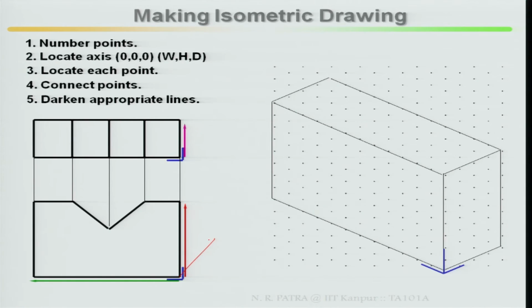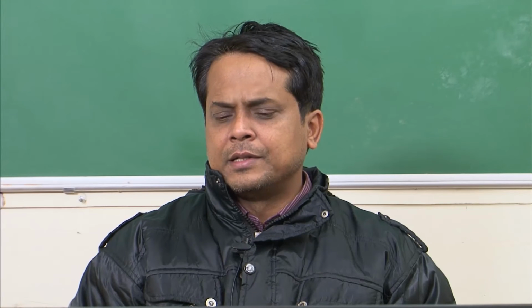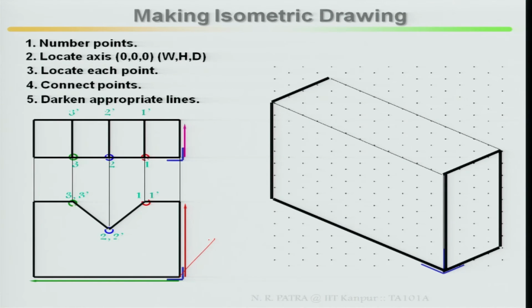It is very easy to draw once you have isometric grid lines. There are two types available in the local market. If you get the grid lines, stick to the one origin. With respect to that, you can take the grid lines. Once your isometric box has been finished, mark the points. So this is your reference or origin. Finish your isometric box, then mark the points.